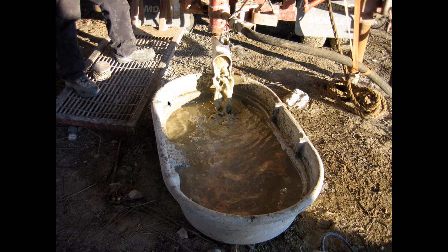And the process is basically this. You put in casing, you over drill the hole with a larger drill diameter. You put in casing to keep it open close to the surface, and then you use a smaller drill steel to drill down through that and keep on going with a rotary drill.